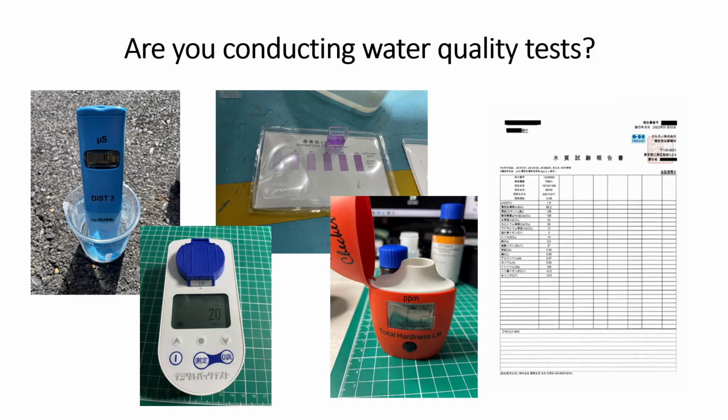Do you know the quality of the water you're using? Have you ever had a water quality test done? I visited many sites regarding cooling water problems and asked these questions to everyone. But in most cases, the answer is, I don't know / I've never done it. You're experiencing problems, but the cause is unknown. However, the cause of mold cooling water problems is 100% related to water quality.